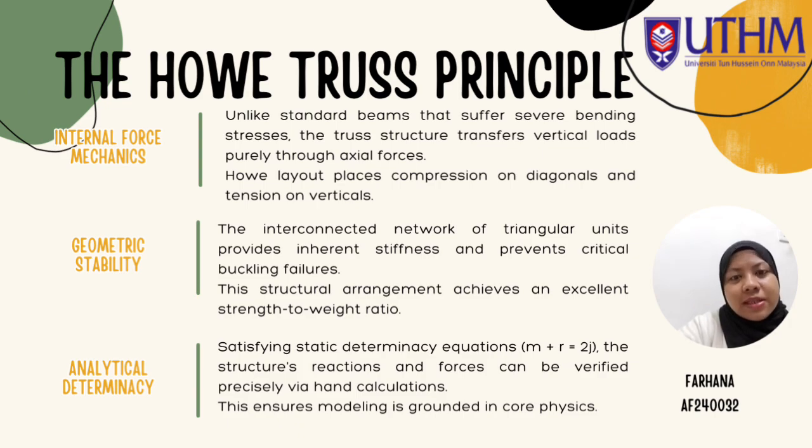Finally, from an academic standpoint, we chose the Howe design because of its static determinacy. By satisfying the determinacy equation, which is m plus r equals 2 times j, where m represents the number of members, r represents the support reaction forces, and j represents the joints, we can mathematically prove that this structure is statically determinate. This means we don't have to guess or rely solely on software. We can precisely verify every single internal member force using traditional hand calculation, anchoring our FEA simulation in core provable